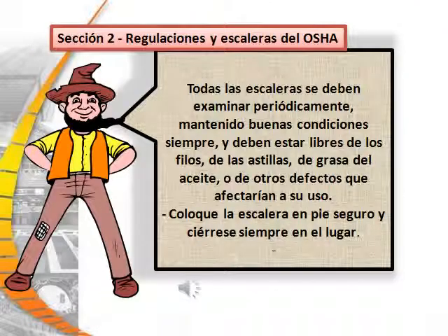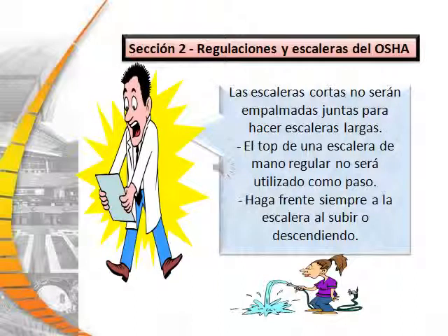All ladders must be inspected periodically, kept in good condition at all times, and must be free of sharp edges, splinters, oil, grease, and other defects which would affect their use. Always place the ladder on a secure footing and lock it in place. Short ladders shall not be spliced together to make a long ladder. The top of the regular ladder or step ladder shall not be used as a step. Always face the ladder when climbing or descending.